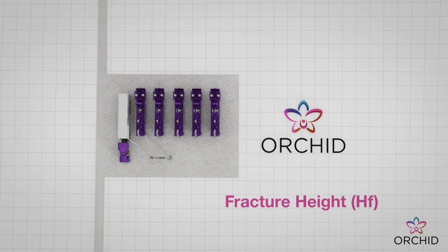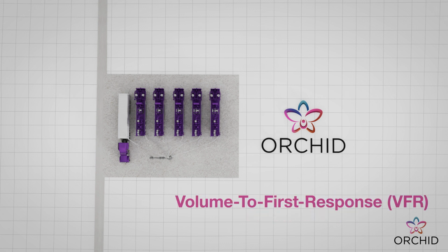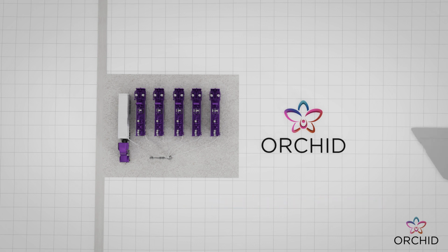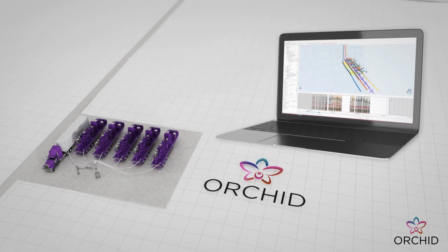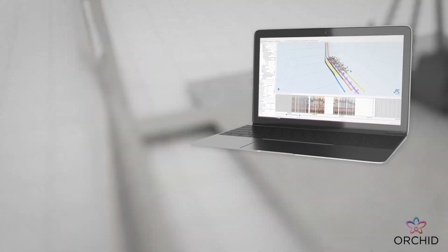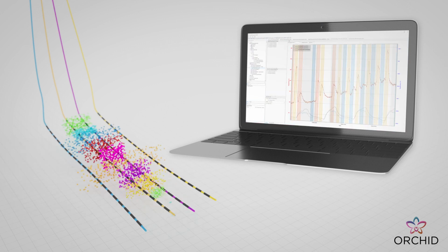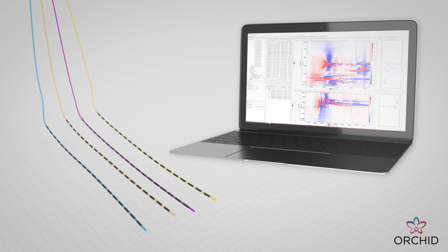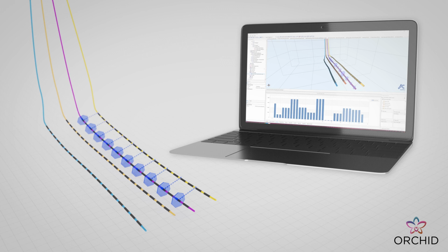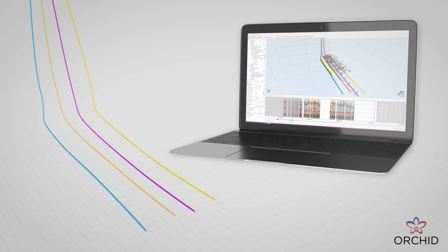When the relationships between multiple parameters are loaded and visualized, outputs from different analyses can begin to make real sense. The surface equipment used in fracking is complex enough, but this is nothing compared to what is happening subsurface. By using different diagnostic types from pressure, temperature, microseismic, DAS and DTS, and tracer data, operators can understand the intricate complexity and geometry of the well and reservoir from which they are producing.